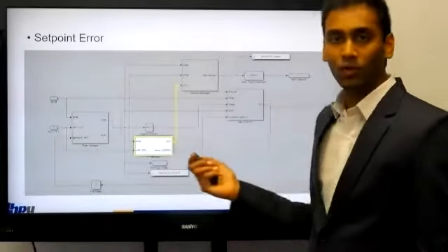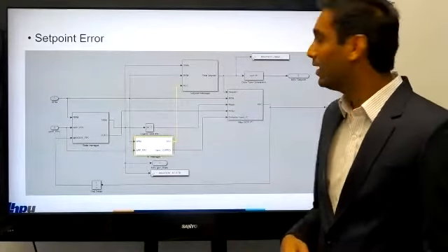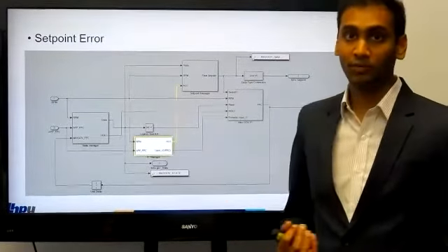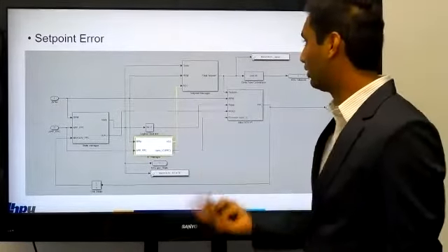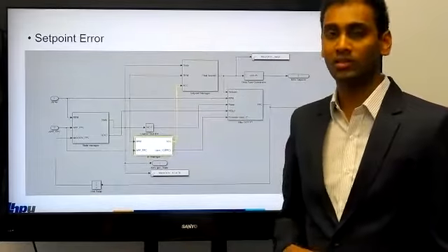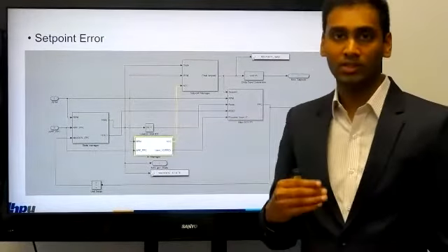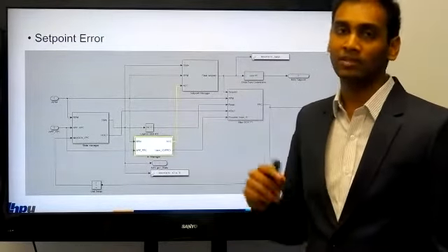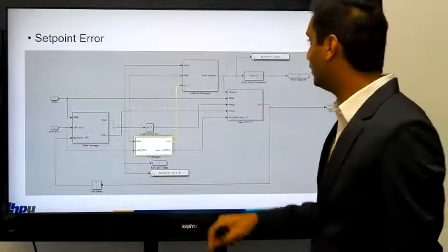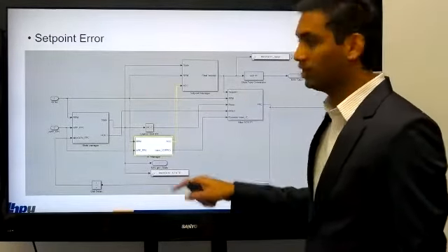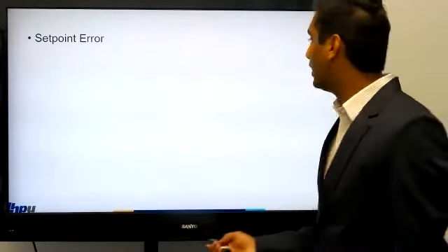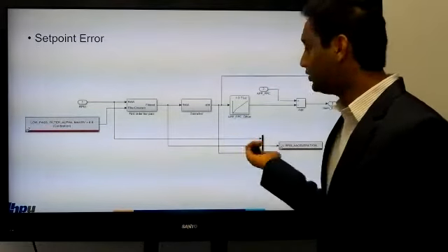And then we traced back what is causing this error. So this is caused by set point. So we had three inputs for the set point. One is the speed, one is the state, and one is the acceleration. The speed is given by the sensor, and the state is active since we could see it working because the max curve is getting activated. And then there's another input called acceleration. So we traced back that acceleration to the initial condition manager, and then we found this.